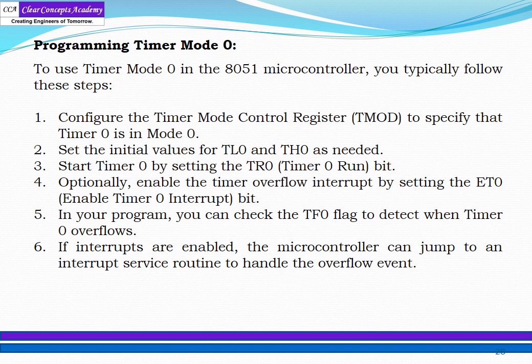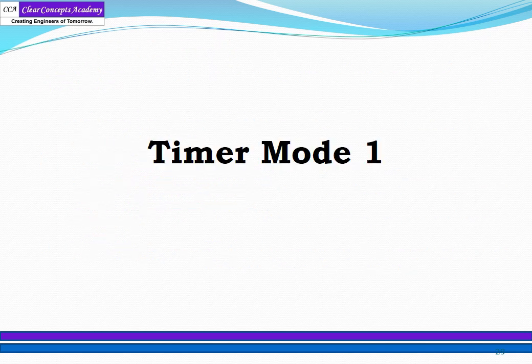Similarly, the interrupt cannot wait till you finish your program. It has to be attended on top priority, so it will immediately jump to the address where the interrupt has occurred, attend the interrupt service routine written there, and then come back to the main program.